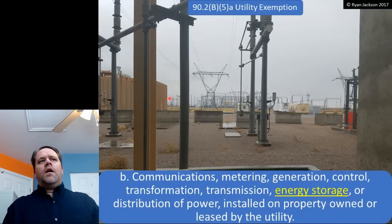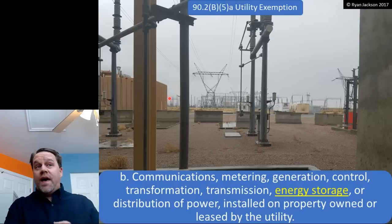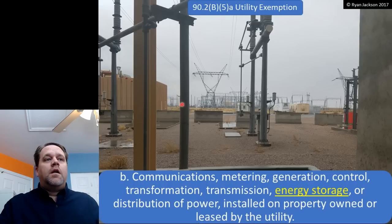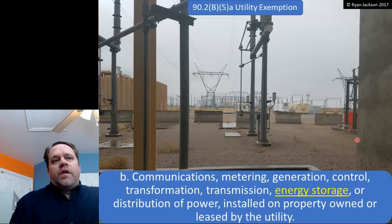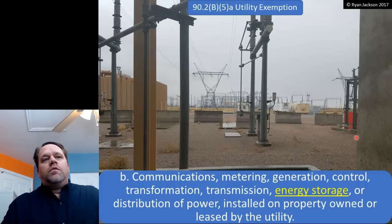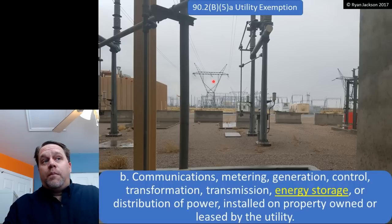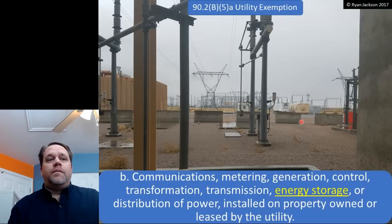All right, moving along. So 90.2(B)(5)(a) said that service drops, service laterals, and associated metering are not covered. Neither are communications, metering, generation, control, transformation, transmission, energy storage, or distribution of power if it's installed on property that's owned or leased by the utility. This is utility stuff. It's having to do with transforming and transmitting power. This is a 500,000 volt line. That's not covered by the NEC. It's on property that's owned or leased by the utility.